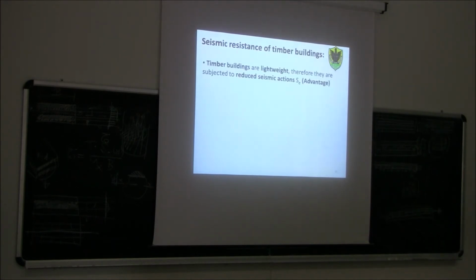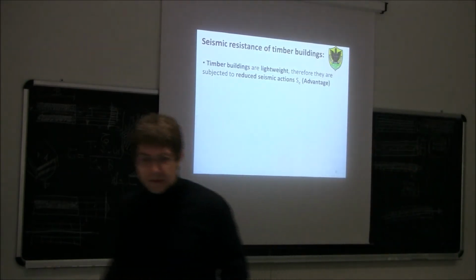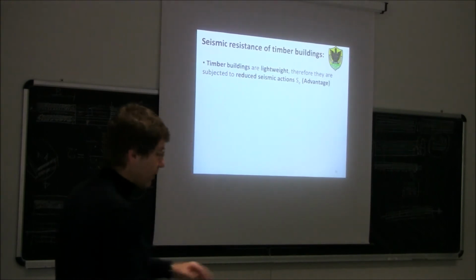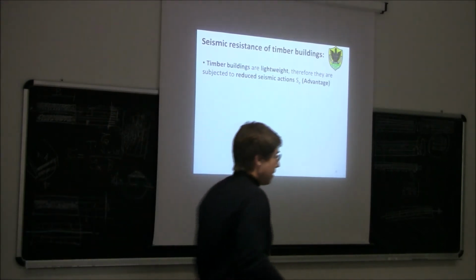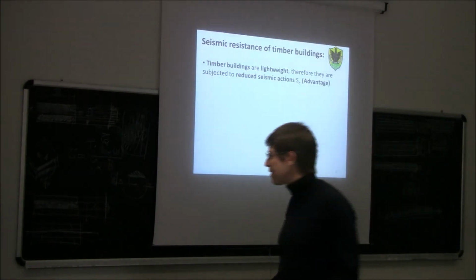Now, some basics about seismic resistant timber buildings. First bullet point, very important, we always need to keep in mind: with respect to reinforced concrete, timber structures are very lightweight. We said from the very beginning that a timber structure weighs more or less one fifth of a reinforced concrete one. And since we learned that the seismic forces are roughly proportional to the weight, on a timber structure I can expect a seismic force which will be much lower than on a reinforced concrete structure. And this, of course, is an advantage.